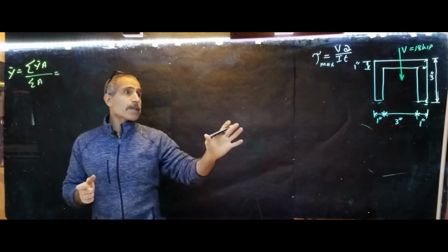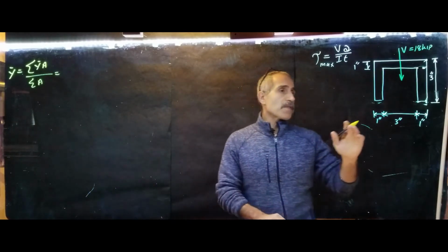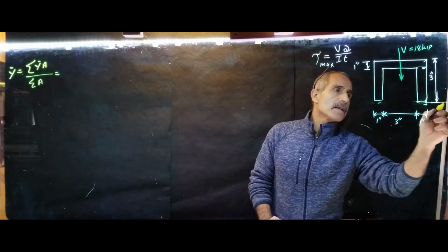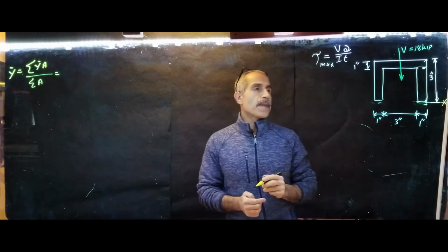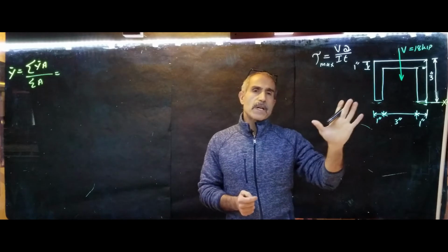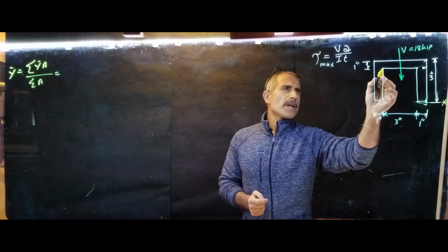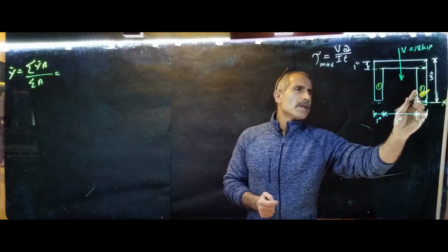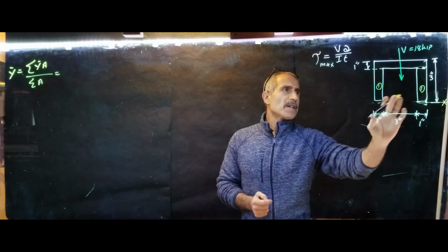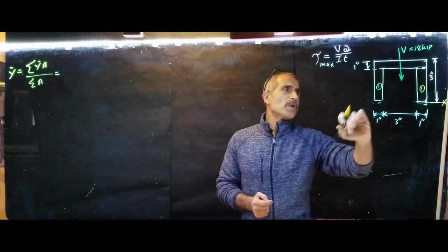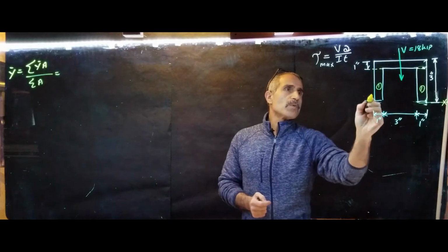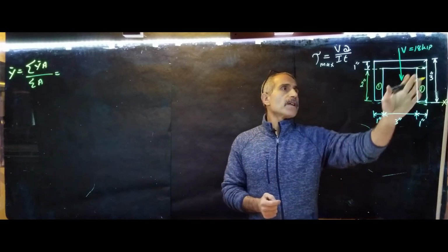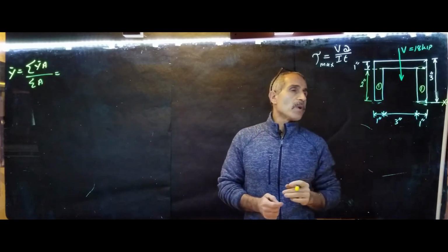Now, when I look at this member, let's measure everything from the bottom here. Let's call this X right here. And we can break it down to three different shapes. The first shape will be right here, this one and 1B. They're both the same thing, both 1 inch wide by 2 inch. So if this is 3 inch, this will be 2 inch right here. And then the third shape will be on top, which will be 5 inch by 1.